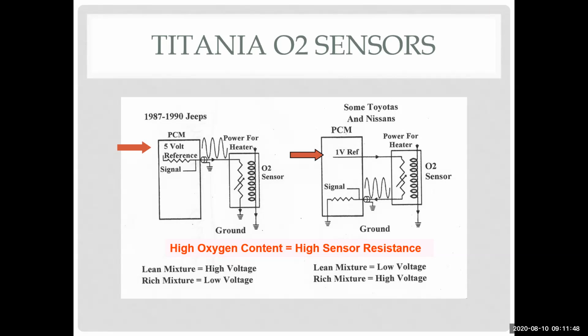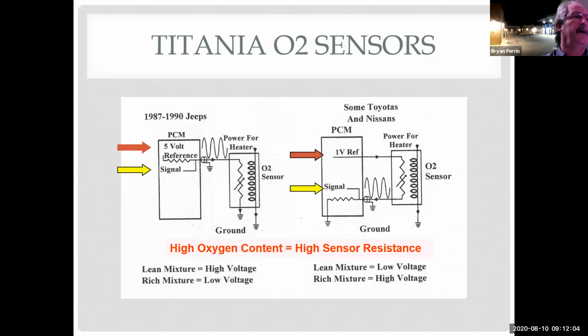Mr. Brian, yeah. On one of the tests, it was asking what voltage it would have, and what I was reading, it's supposed to be 1 volt, but the right answer was up to 5 volts. What, for an O2 sensor? Yes, for an O2 sensor. Yeah, and really, they should have specified what kind of O2 sensor. Because for any kind of O2 sensor, it could go to 5 volts because of these 3 years of these titania sensors. If I specified a zirconia sensor, it would be 0 to 1 volt.